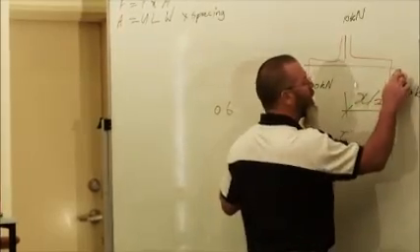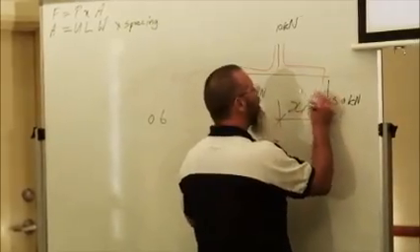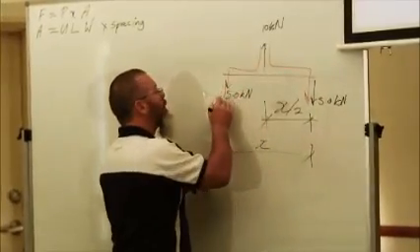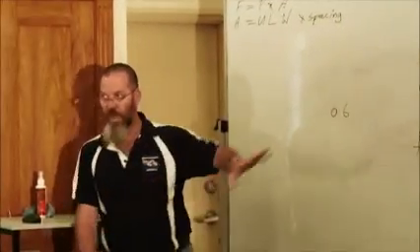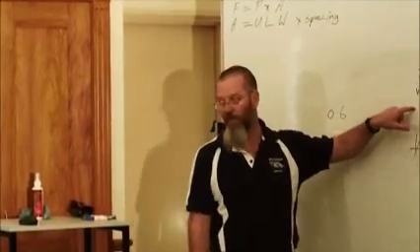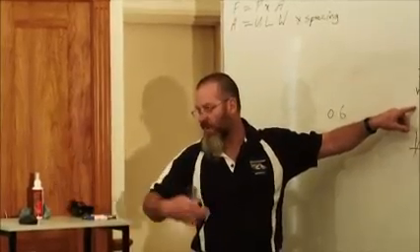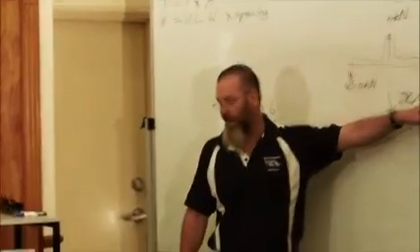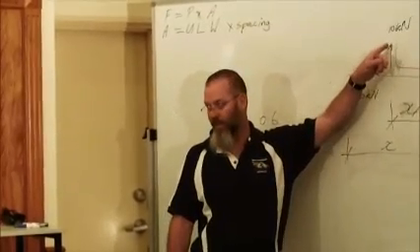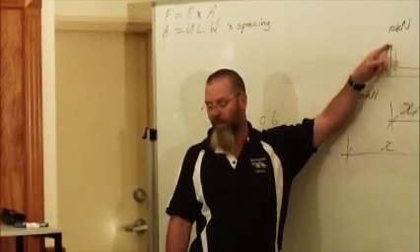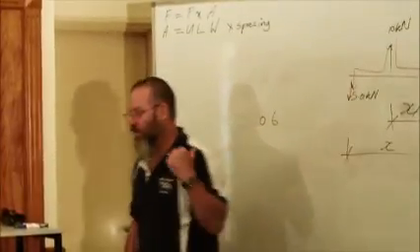Now that's beam design. I want to keep it really simple because we're builders. We're basically simple people. Don't be offended by that. This is tie down. Just reverse the directions of the arrows. It's not that technical. In theory, if I had a crane here and I had a spreader bar with 5 kilonewtons or 500 kilos this side, 500 kilos that side, obviously I'd be lifting 1,000 kilos in the centre. If I could get it exactly right in the centre, I could lift that. That's all tie down is.